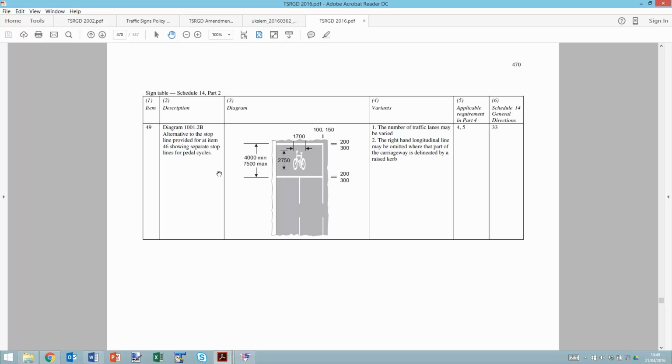Now, essentially, this goes back to a point I was going to make later about the savings. So this essentially now prescribes that kind of layout if you've had one in place for some time. I've certainly seen this layout quite commonly around the place, where a little cheat perhaps with the diagram number, sorry, the dotted line I should say, is used as an entry point so that cyclists didn't have to cross the stop line.